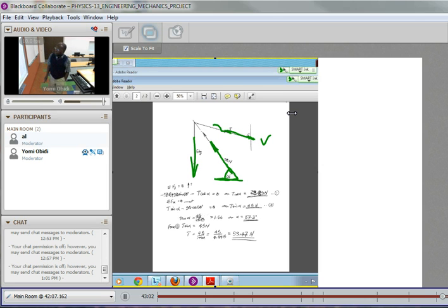So let's sum the forces in the y direction. If we sum all the forces in the y direction, we have the 5 kilogram, which is 5 times 9.81. That's the weight dropping down or tending to drop down. The y component of this 90 Newton force is 90 sine 60 degrees. And the tension, this is alpha. We don't know alpha, we don't know T. So those are the things we're looking for. If we take this component of T, that would be T cosine alpha. Okay, so that's T cosine alpha, and that's what's represented there.